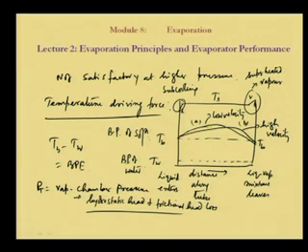So initially the temperature is high, it is heated up but not boiling, and once it starts boiling its temperature reduces afterwards. Because the velocity is low, boiling starts somewhere in the middle of the tube, and when the velocity is high, it boils somewhere towards the end of the tube, or may not boil in the tube at all.